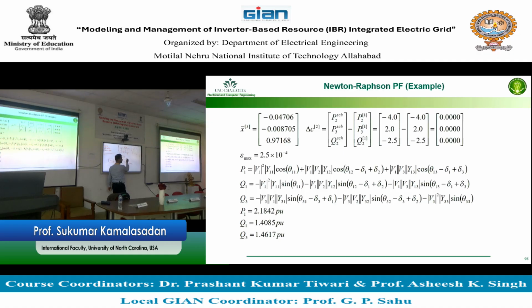So this voltage, if you do the forward backward sweep, I think there is something that we did not do. We used 2400, right? We did not convert into per unit. Remember, I think we did actual. Better to convert in per unit. So 2400 will become 1. So with 1, we did the forward backward sweep. Instead of 1, you should do it with this voltage.